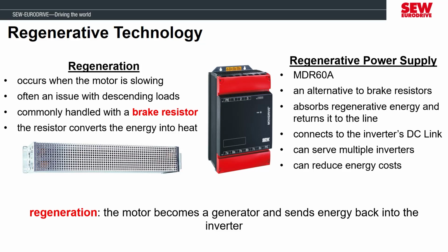It can save a considerable amount of energy over time since we're recapturing energy that the MOVIDRIVE has had to put into the application. The MDR is an investment, so you will need to determine how much energy is being wasted by a resistor and what the return on the investment will be over time of reclaiming some of that energy. There are several sizes of these, but the smallest one is rated for a 15 kilowatt load, so the MDR will have more benefits for larger power applications than the smaller ones.